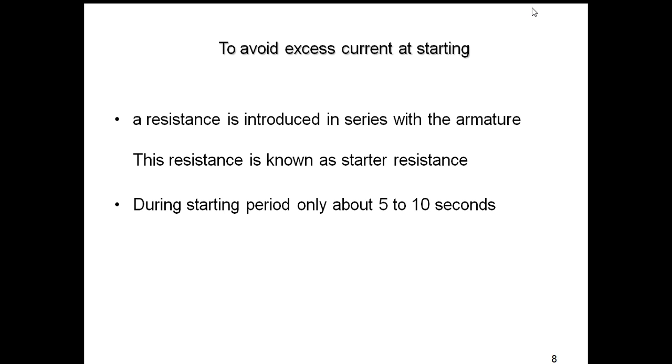During starting period, we connect this resistance only up to 5 to 10 seconds, and this resistance will limit the starting current to a safe value.